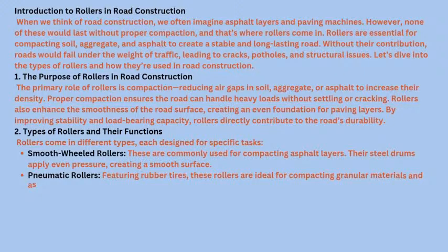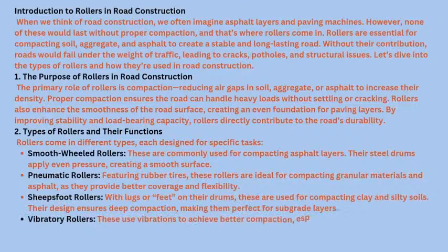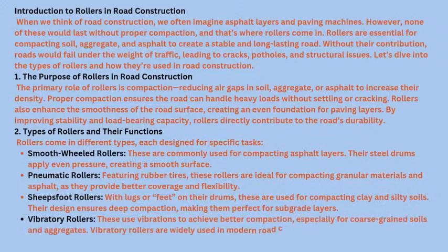Sheep's foot rollers, with lugs or feet on their drums. These are used for compacting clay and silty soils. Their design ensures deep compaction, making them perfect for subgrade layers. Vibratory rollers. These use vibrations to achieve better compaction, especially for coarse-grained soils and aggregates.